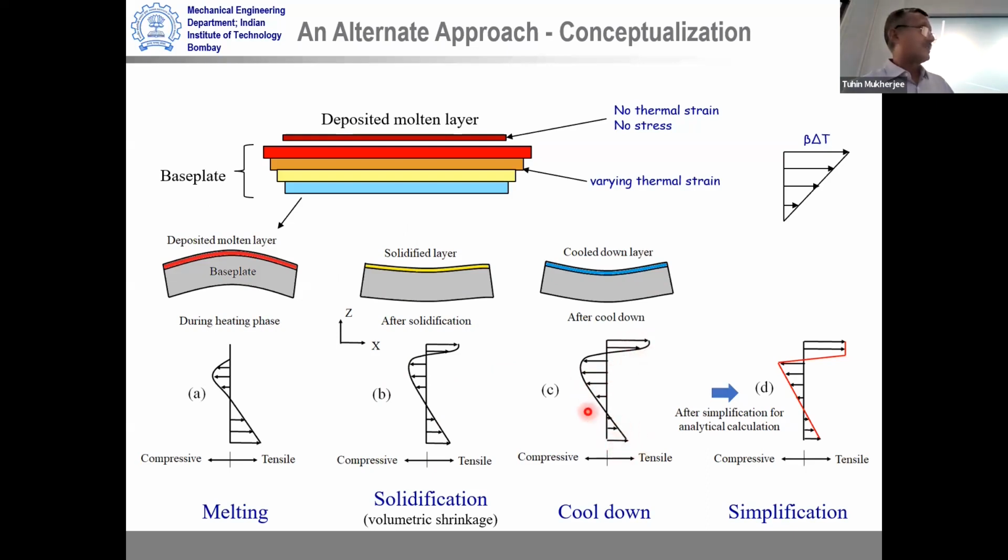So imagine a situation, if this is the distribution of stresses that happens for the deposition of one layer on a typical substrate, perhaps it's not so bad if we just think it. It's a little simple, a little bit of constant through the thin layer. Now remember, in laser powder bed fusion, the layer thickness is not really so great. So perhaps we can think of this constant, a linear variation from here to here to a maximum compressive point, and then going further down to the tensile state as it will be equilibrated. Now the question is, this evolution needs to be captured in a manner that comes out of a mechanistic relation, equilibrium of forces, equilibrium of moments because of expansion and contraction.